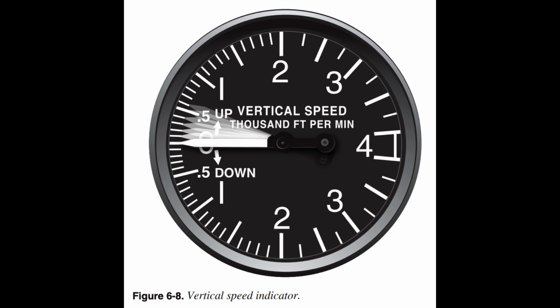During climbs or descents, the VSI is used to change the altitude at a desired rate. Pitch attitude and power adjustments are made to maintain the desired rate of climb or descent on the VSI. When pressure is applied to the controls and the VSI shows an excess of 200 FPM from that desired, over-controlling is indicated. For example, if attempting to regain lost altitude at the rate of 500 FPM, a reading of more than 700 FPM would indicate over-controlling.